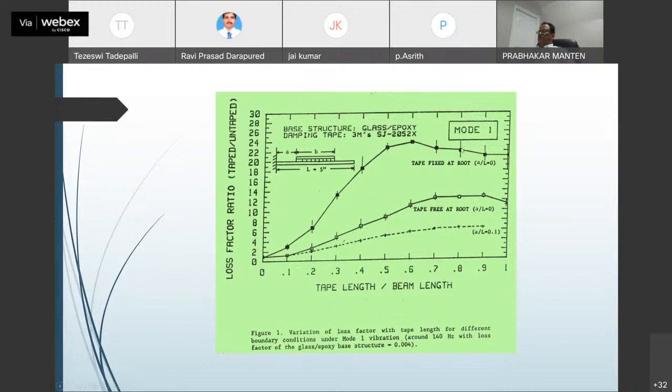Extremely high damping was provided by doing this. So there is a lot of increase in damping. Usually if you add any damping, you have a tendency to lose the stiffness. That's the very nature of things: high damping means low stiffness for typical materials. The goal is to not lose too much stiffness, but have that additional damping provided.